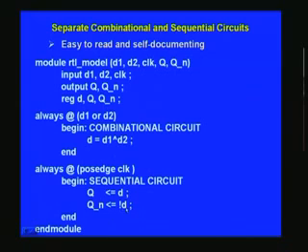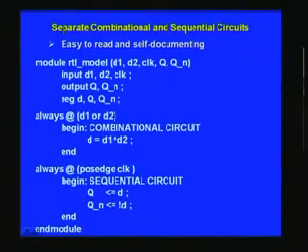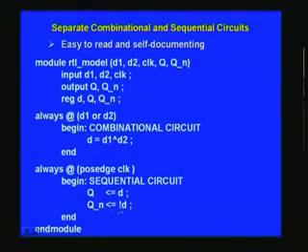So here we are inverting this D, although actually you will be surprised in the synthesis tool to find two flip-flops there, not just one flip-flop. Our intention was just to make one flip-flop, and the other one is merely an inversion of this. But unfortunately, the tool has not that much intelligence. As a designer, you have to know the limitations of the tool, and then find ways and means to circumvent those limitations. One way to circumvent is don't put this statement here, and use an assign statement outside, and say assign q underscore n equal to exclamation mark d, or you can even put a tilde here.